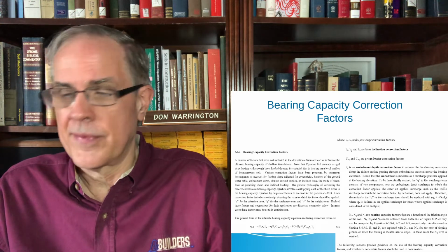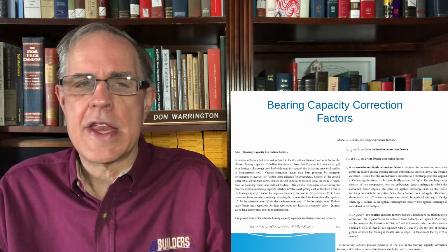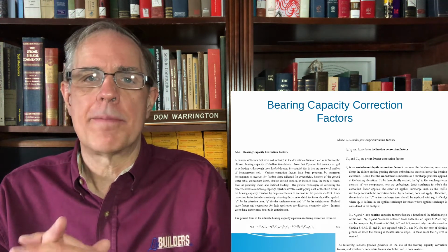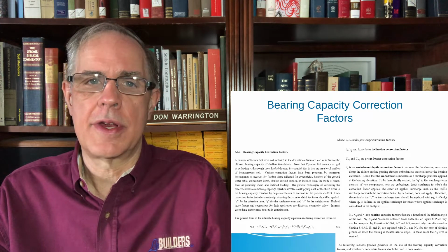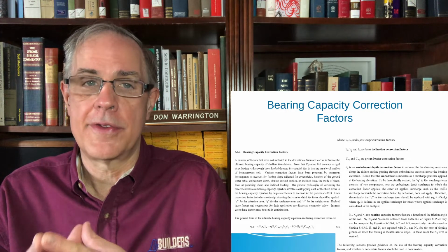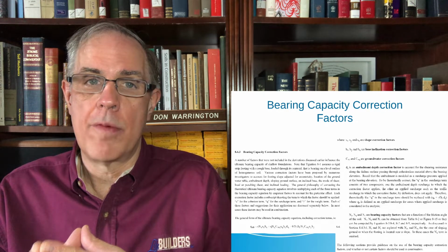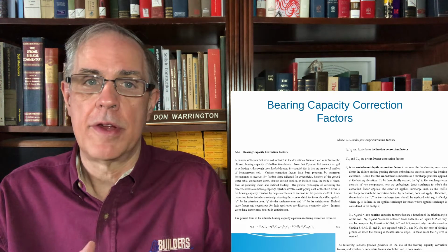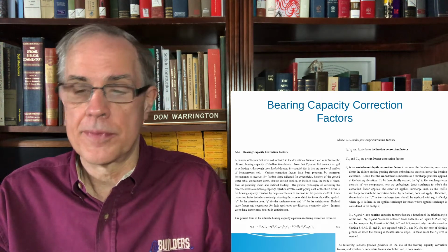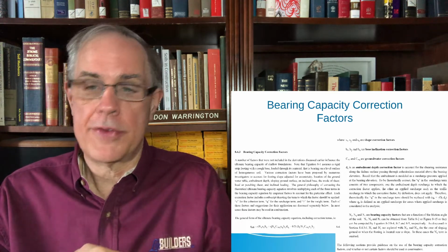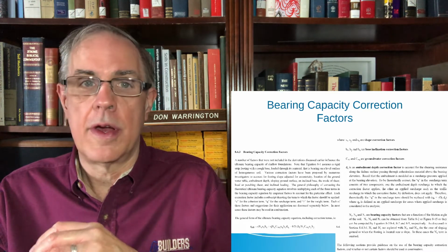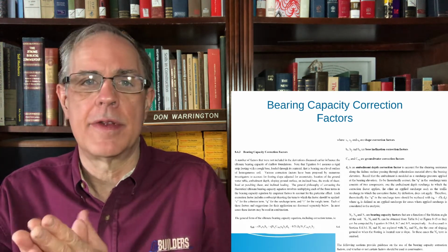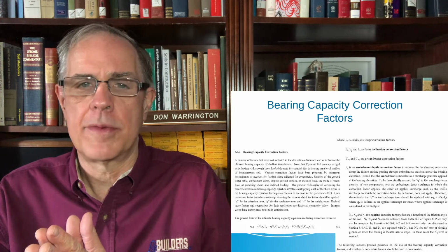Correction factors. Once we get past the conditions that we used to develop the theory to start with, the lower bound solution pretty much is in the rearview mirror. We're strictly dealing with upper bound plus some kind of factor of safety. With bearing capacity solutions, however, we use the correction factors to extend bearing capacity, and this can get tricky sometimes.